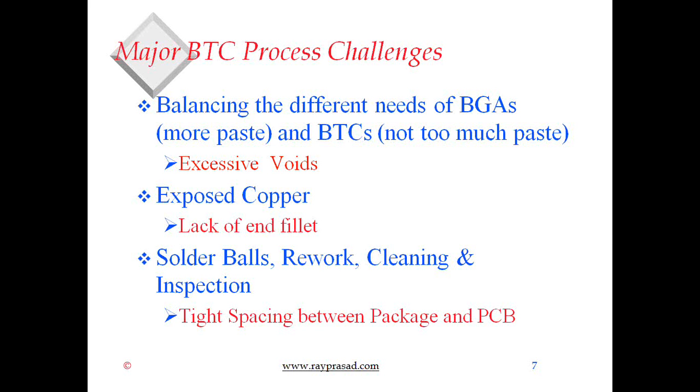The ends of those terminations are basically exposed copper, and that presents a challenge about whether we need the toe fillet, because you really can't get a toe fillet. Some people might want to reject those joints, and if you do, then you have a problem, because you can't really reject them, given the way the package is made. So how do we deal with that?